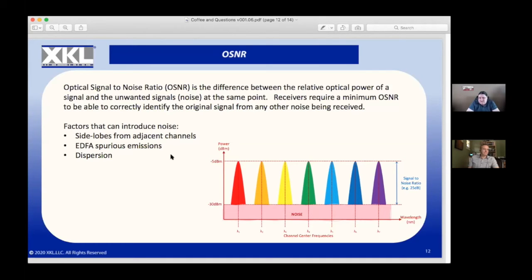And it is absolutely almost a good half hour's chat about the different types of coherent technologies and how it's evolved, how it works. Because coherent services is one part of the industry where it's not exactly a perfect standard. Some manufacturers have developed their own, called DSPs, digital signal processors, that go into the equipment to modulate the signal, to put all the coding and things, and to work with forward error correction.